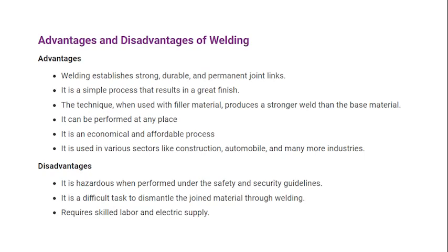And the filler material you use will be stronger than the base material, because when you are directly solidifying your filler material, it gives you a kind of quenching effect. That is why your weld will be stronger most of the time. It is also an easy process that can be performed at any place. It is economical and affordable.